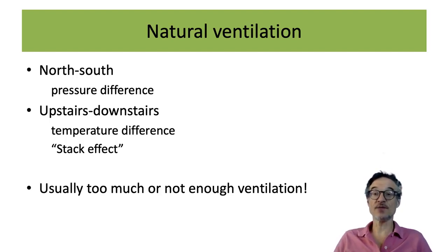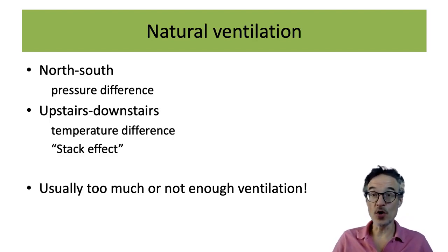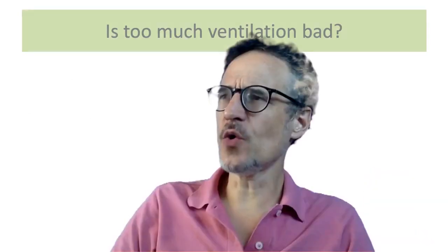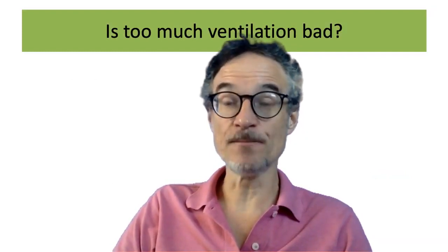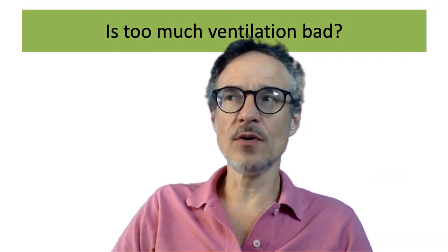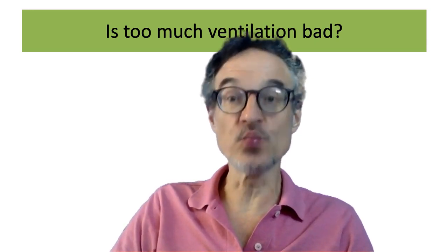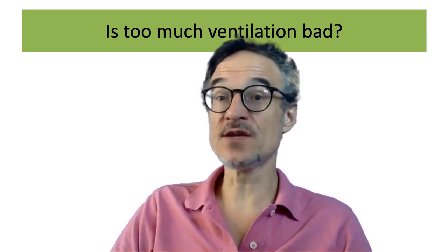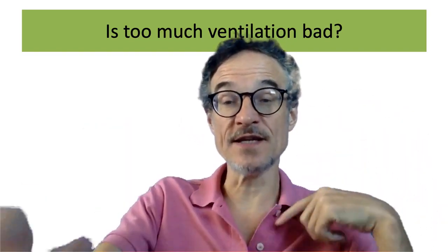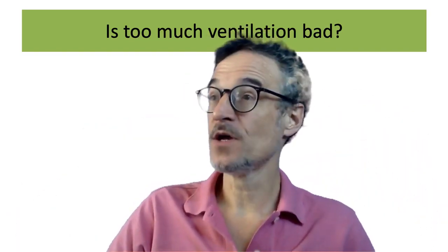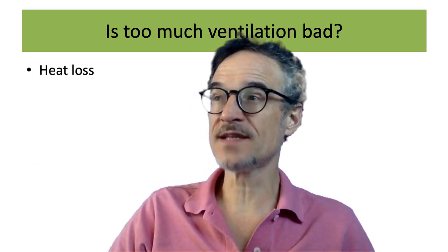If we're trying to get a target amount of ventilation, if it's very still, then we may get no ventilation from opening these windows. And if it's very windy, then we may get too much ventilation. So is too much ventilation bad? Well, remember that if it's winter and it's warm inside, we have lots of nice warm air. So as we're ventilating, we're losing all of that air. So one reason ventilation is bad is heat loss.